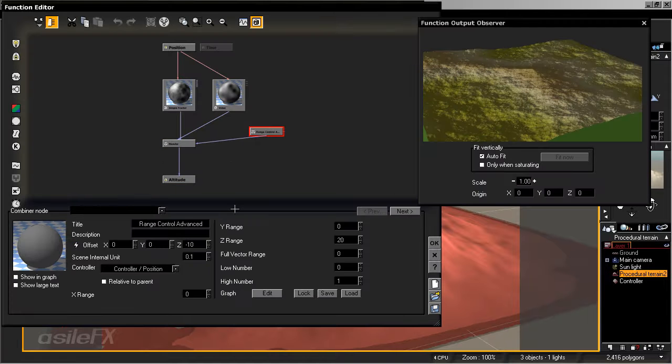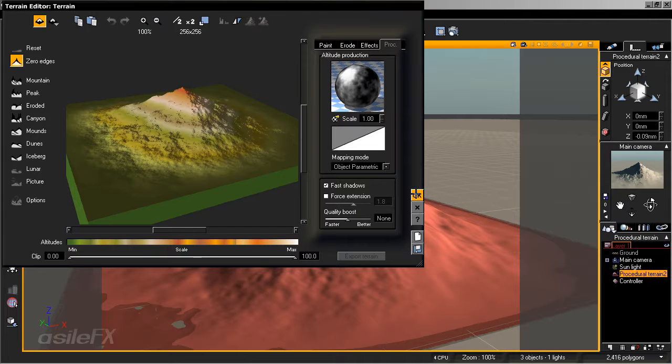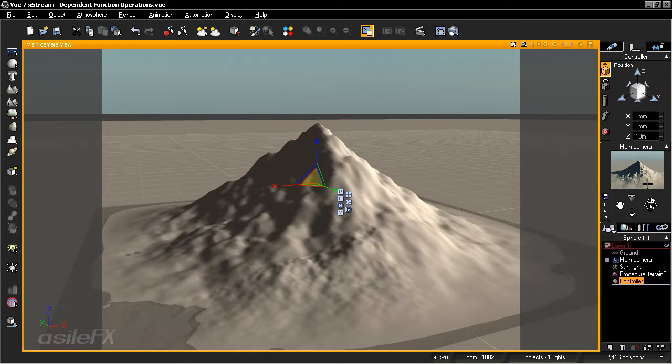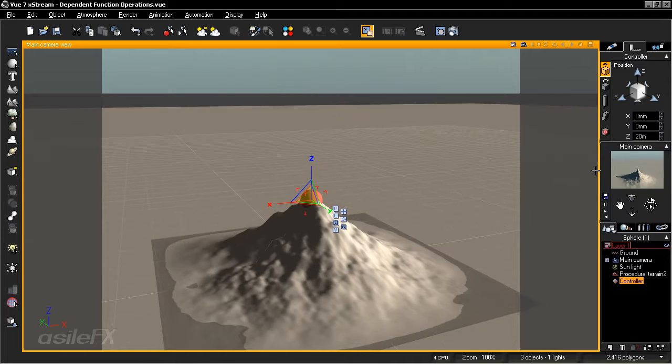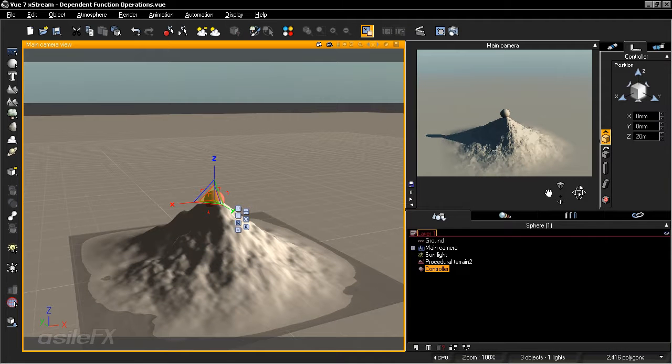And we're going to set that range to -20. Now I'm using negative because I'm going to be moving the object in the positive range. So by setting a negative range, we're subtracting that initial movement that we have. So let's go back to our controller, set this to 20, and now we can see it showing up in the scene. And because our procedural terrain is not going to refresh, I'm going to open up the preview on the side, and let's take a look at our control.